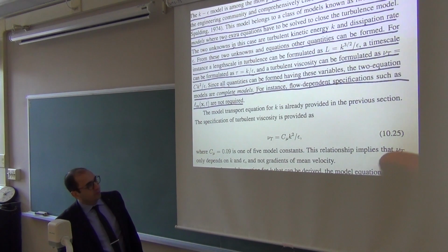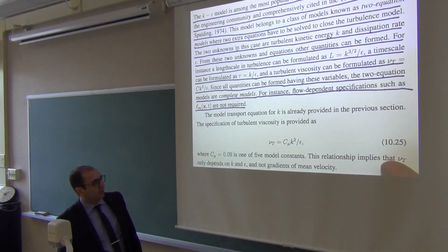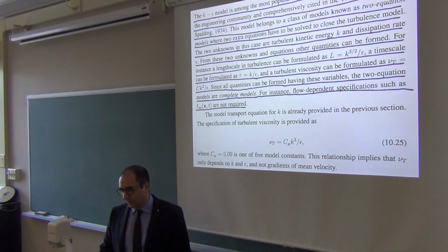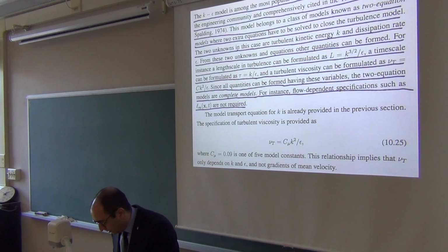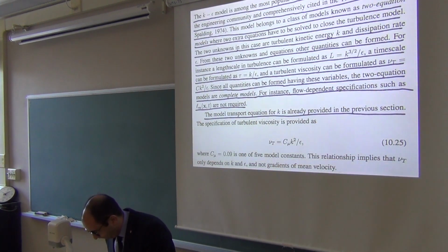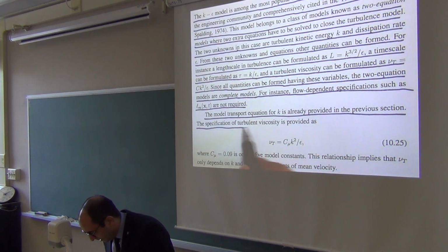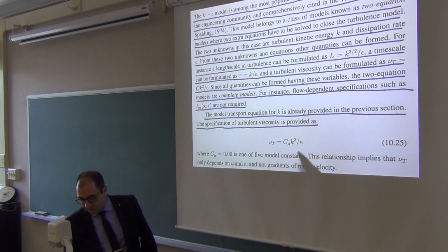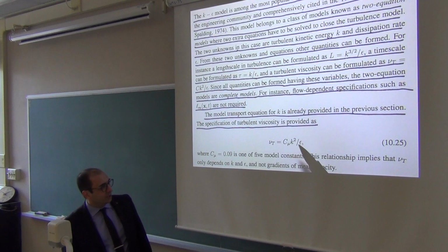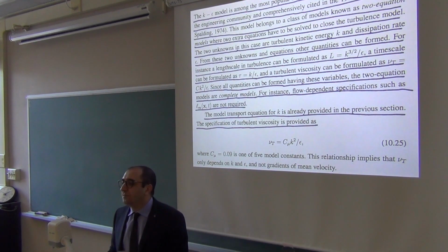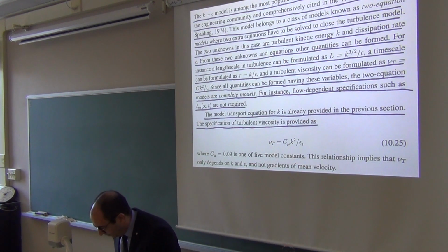We provided you the transport equation for turbulence kinetic energy already, so that was the last page. So that equation is the same. It's not any different in this model. But what's different here is turbulent viscosity is defined, as I said, using this relationship, and then C mu is a new constant, which has been fitted for the model.